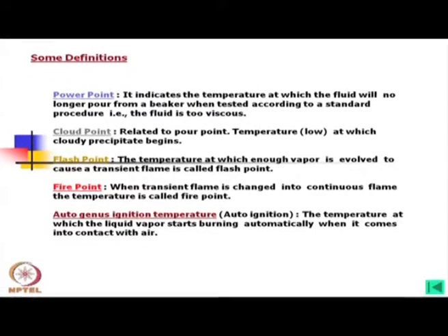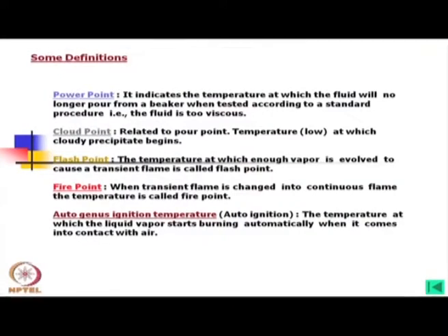In winter, the oil temperature may be as high as 65 degrees centigrade, whereas your ambient temperature is maybe within 20 to 25 degrees centigrade. So, we have to maintain this temperature for the safety of the machines as well as for performance, because if the temperature changes, viscosity will also change, and you need very accurate control, which will affect the operation.